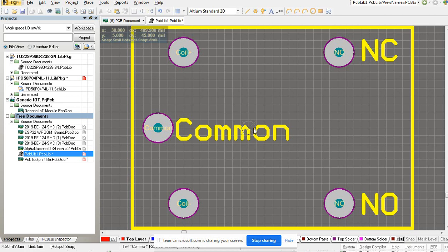Now what I have done, I have selected the center over here. So whenever this library is going to be held in my PCB file, it will be held from here. Now almost everything is done, just one thing is remaining which I will tell you afterwards.